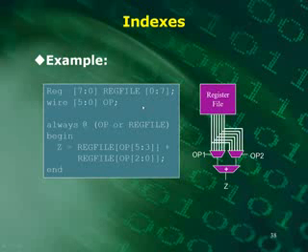Here's another example that's synthesizable. Here I have a little register called reg_file. It's 8 bits wide and 8 deep, so it's like having 8 memory locations, 8 bits wide. Then I have a variable called op, which is 6 bits wide. I said always at op or reg_file, so anytime anything in the register file changes, or anytime the variable op changes, we come into here.